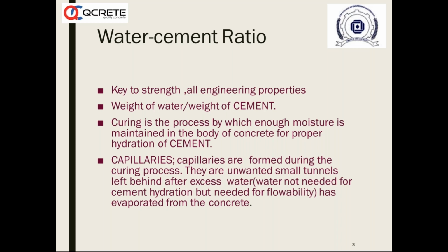What is hydration? Hydration is the reaction between cement and water. So if the water has to mingle and react with cement in the concrete, it has to be prevented from escaping into the atmosphere through evaporation.